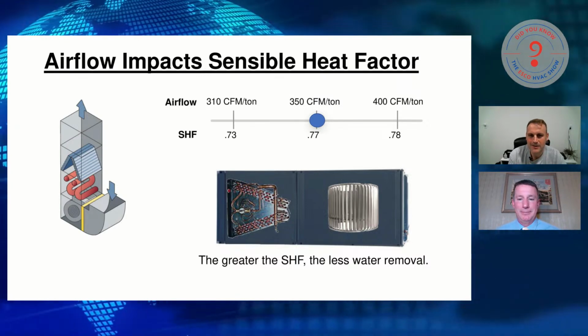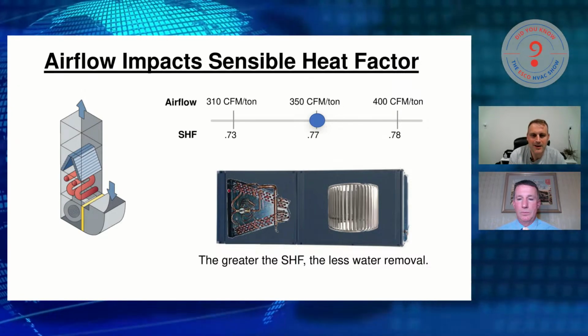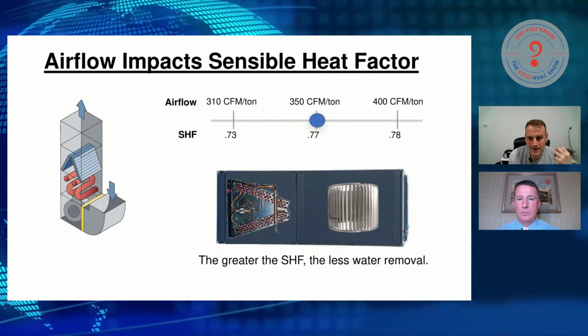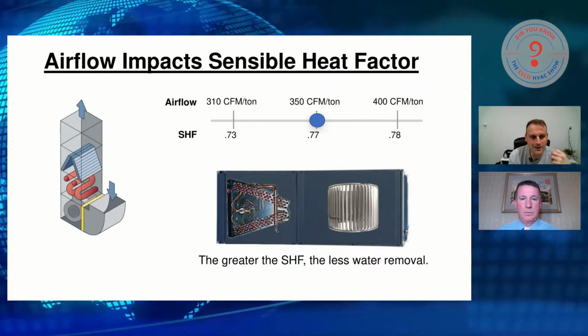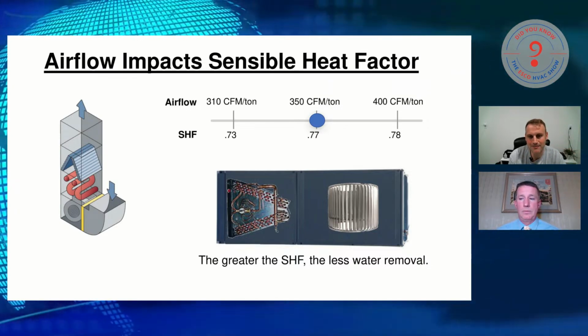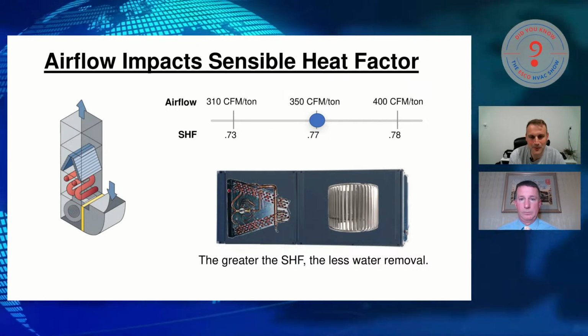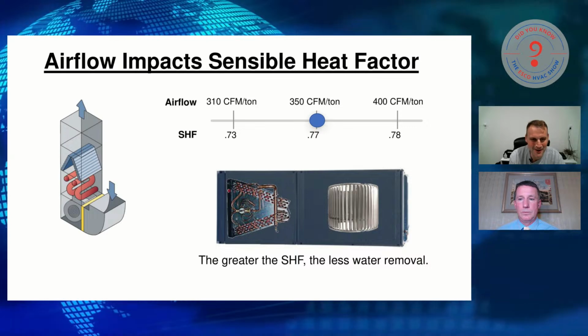Right. So make it short and sweet. This is just a little screenshot picture I'm putting there. And all I'm saying is if you walk into a home and that home is not feeling comfortable, it's muggy, there's too much moisture in the air, could it need a full-blown investigation? Yes. But would I start checking airflow? Yeah, probably would.